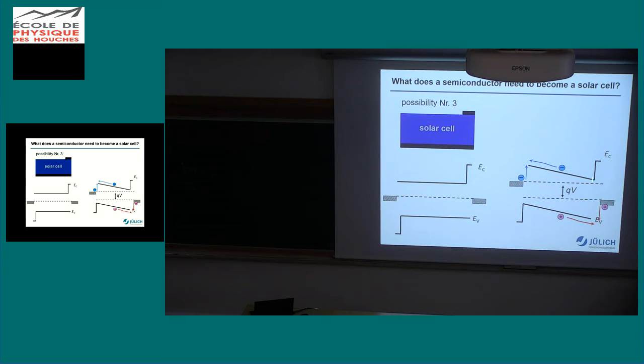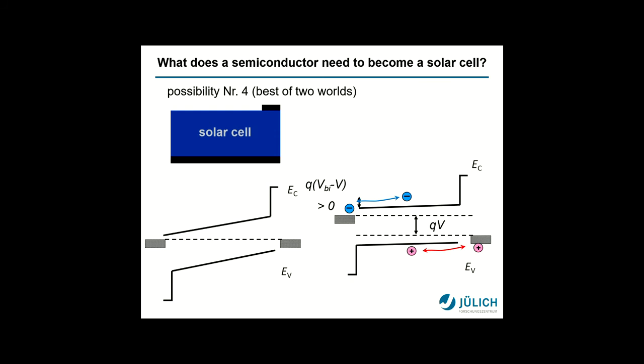They cannot get out here. That's a benefit of the wall. And then finally they get out. The other thing is, for the injection, that's still always the same barrier, so that's not modified. So it's quite an interesting situation, but it's not really robust in the sense that if you have a little bit low mobility, a little bit low lifetime, this will not work.